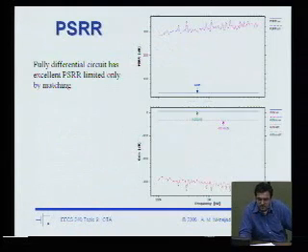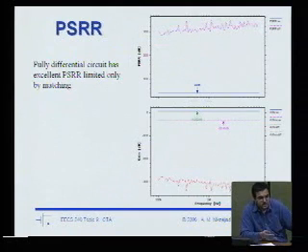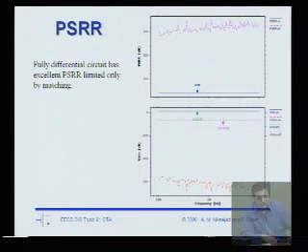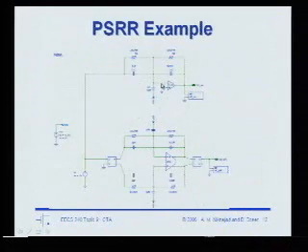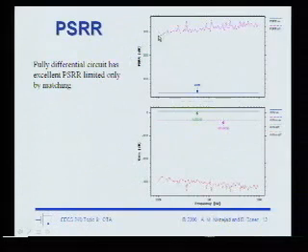Well, it's probably then some cap divider, right? Because cap divider's frequency dependence drops out, and so it's more or less flat once you get up to a high enough frequency. So if you look in here, for instance, there's a cap divider at the input with this capacitor. And so if there's any capacitance from this point to VDD, that's going to generate a signal from supply.